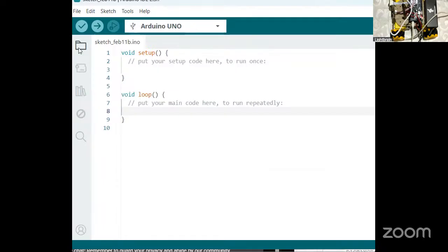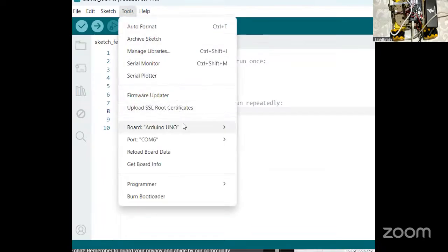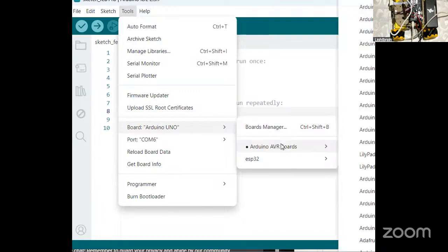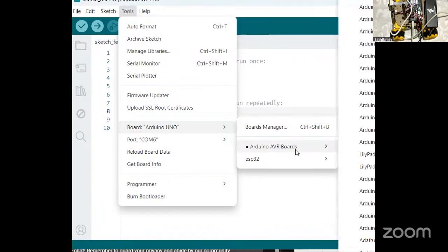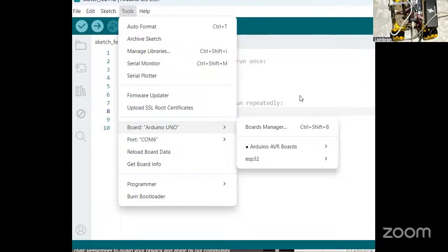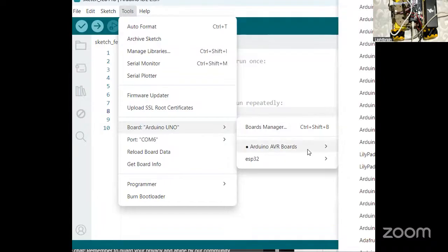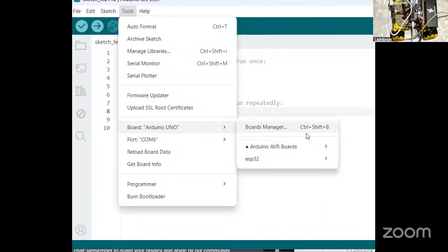And then you can just select this one. You go to board. If you haven't selected anything, when you click on board, it will take you to the place I was saying to select Arduino. As you can see, for me here now, I've selected Arduino already. Whenever I select Arduino UNO, sometimes it won't display Arduino UNO, but it may write Arduino AVR boards. It's still Arduino, so do not worry whenever you don't see it. Okay, this is how we know that it's working.